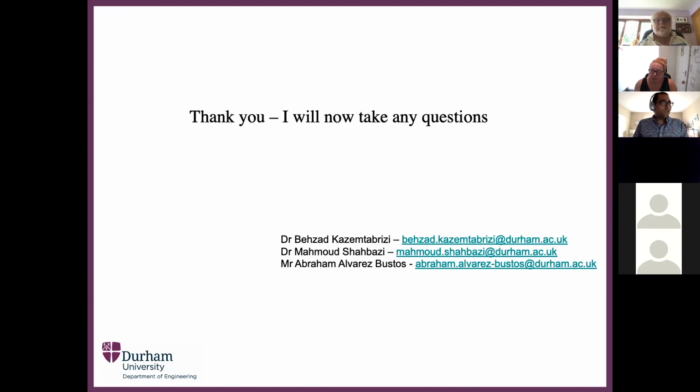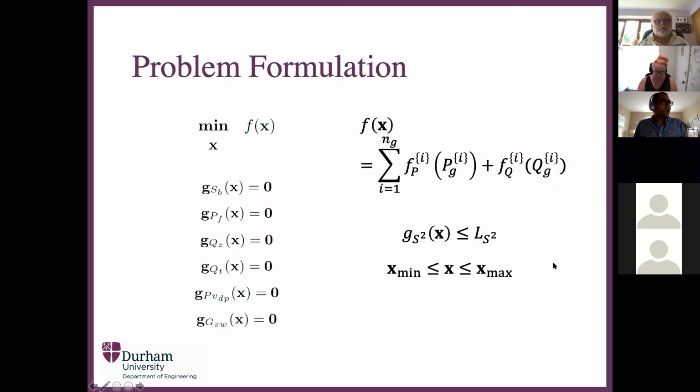So in the normal OPF, in here, you do already have the losses in the network integrated. So yes, you can just change the objective function to losses in, let's say, an offshore wind farm, and then solve and see whether or not your state variables will give you that minimum loss solution.